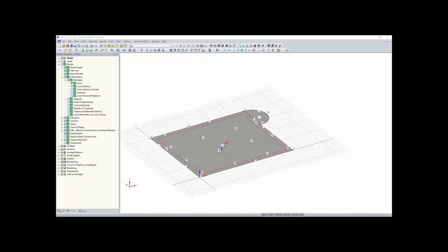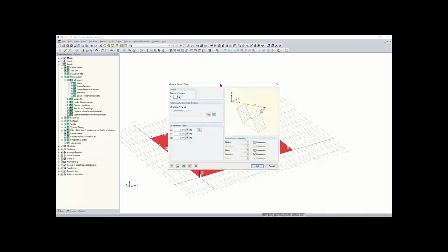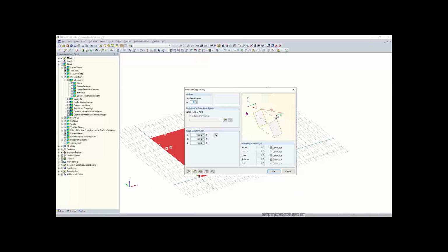And so now, after surface 2 has been created, we can work on our ceiling slab. This should be pretty easy since our ceiling slab is going to be symmetrical, or basically the same as our floor slab. What we can do is highlight our floor here, and then we're going to move and copy it. Something to keep in mind is that there's going to be a clear height. So for example, for this concrete building, there's a clear height of 11 feet between these 2 slabs, between the floor slab and the ceiling slab.